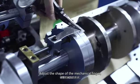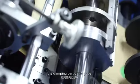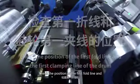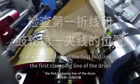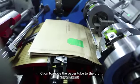Tighten the screws of the open side mechanical finger fixing seat. Adjust the shape of the mechanical finger so that it can smoothly pick up the clamping part of the paper tube, and then the paper tube moves smoothly to the guide plate. Check the position of the first fold line and the first clamping line of the drum. Rotate the machine in an inch motion to move the paper tube to the drum.